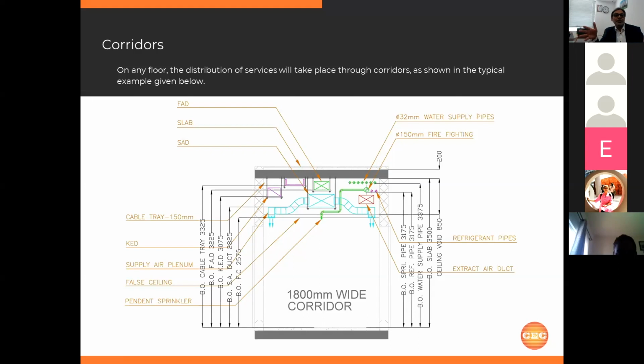If we reduce the corridor width to 1.2, then the height increases a little bit. This typically goes with the distribution ratio of the floor to floor height. Architects need to have maximum height for their aspect ratio, etc. So the floor height is getting governed by the services and the height the architect is looking for.